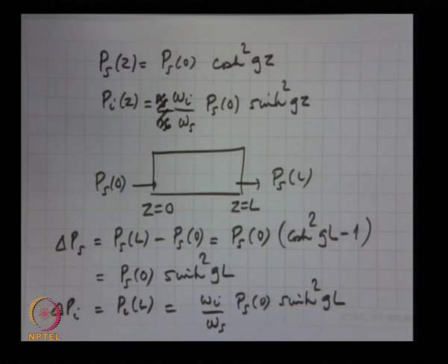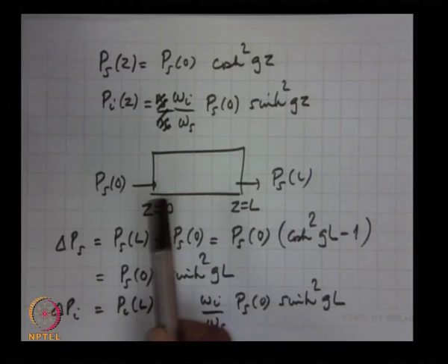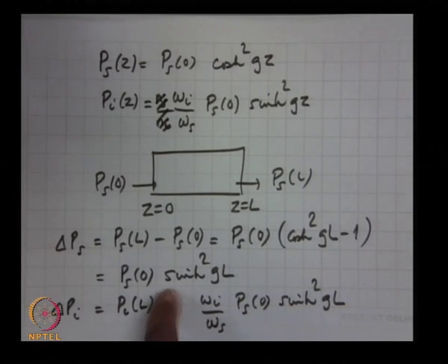And because the idler frequency is usually smaller than the signal frequency, the power in the idler is smaller. It has the same number of photons as the additional number of photons in the signal, but because its photon energy is smaller, the power in this idler is smaller than the power in the signal, assuming omega s is always bigger than omega I. So this factor comes simply because of having the same number of photons generated at the idler and signal by this process. Every time I add a photon in the signal, I add a photon in the idler. The photon at the idler has a lower energy, and hence the power coming out of the idler is smaller than the additional power being generated at the signal frequency.